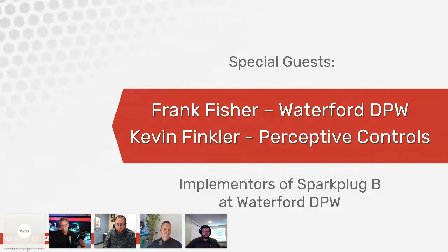So the big advantage to us is we had sites that we needed data back from, but there was hardly any change. It was a really low flow site. We might not get any data for an hour, but still we're polling it all the time. What this allowed us to do is, other than the small heartbeat that goes to make sure that the connection is still there, it's not passing data unless something changes. So that was huge for us. And it still amazes us when data comes in instantaneously. You're so used to that polling protocol.